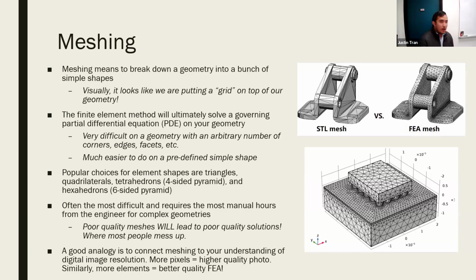Okay. But a very simple way to think about your mesh is that the smaller your elements are, the more accurate your simulation is going to be. Okay. Think of it like the resolution on a photo. The more pixels there are in your photo, the higher quality the image is going to be.